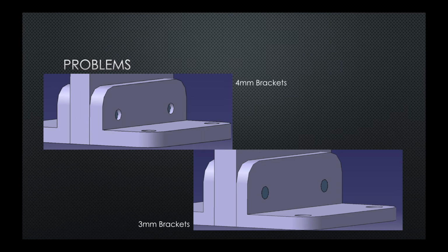However, when the fasteners were added later in the project cycle, it was found that the length of the fasteners given did not fully reach the end of the second bracket. We then updated the bracket width so that the fasteners would fit properly.